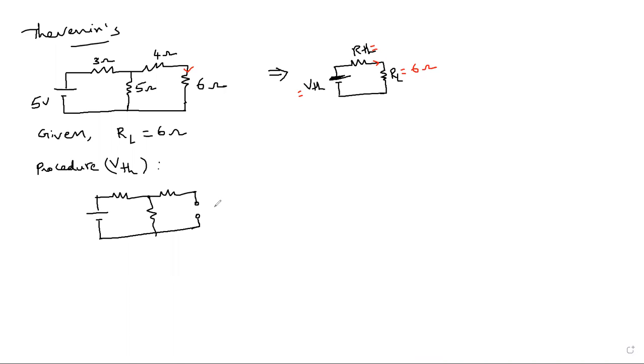So for this, we need to calculate the value of voltage, that is your VTH. That means this one. So calculate your VTH, and also calculate RTH. Find out the value of VTH and the value of RTH.